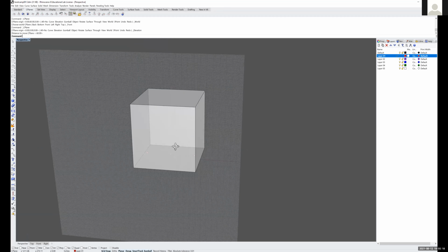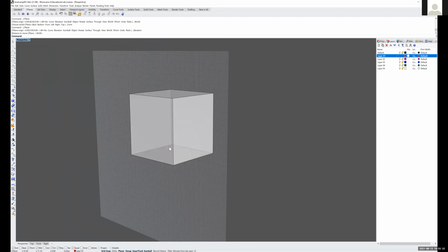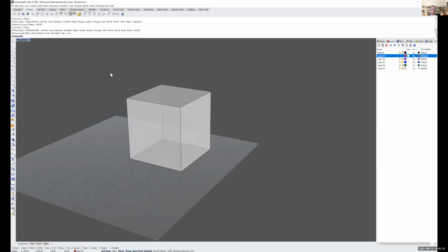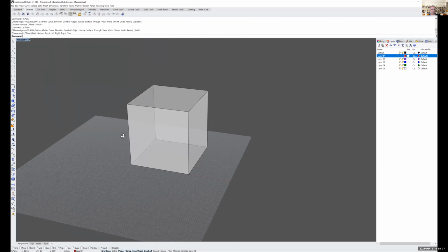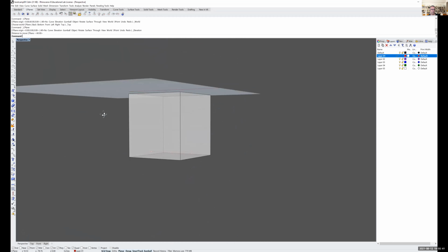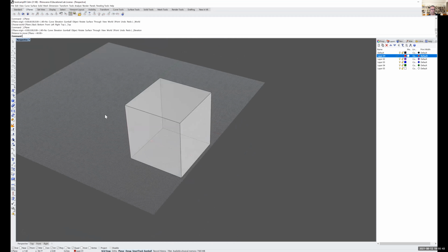So first you select the facing that you want, and then you hit set C-plane? Yeah. And if we wanted to work in plan, which we will in a second, and draw something else, we can then change the elevation in plan and have it move up or down.